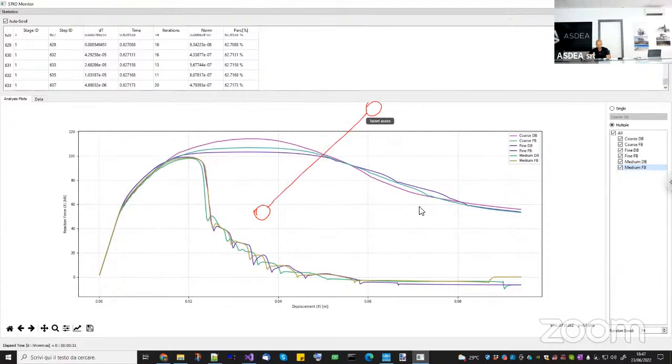As I said, in OpenSees, the characteristic length is defined for every kind of element as the minimum distance between two consecutive nodes. Okay, so for a beam element with two nodes, this is the characteristic length, L_ch. And it is the same for displacement-based and force-based element.